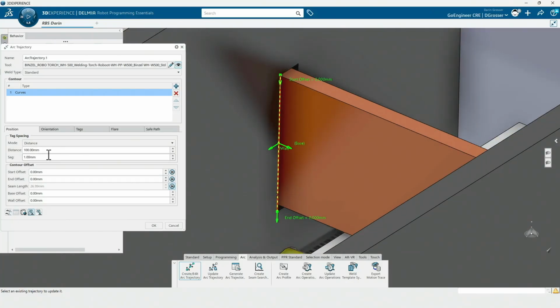From there, we've got our start points and our end points. And when we're defining things, if you're comfortable over here, you can define the start offset, the end offset, and the overall length. One of those three always has to be driven, though. So you have to choose whether you want to have offsets drive the length or one length and one offset drive the other offset. But there are on-screen handles, and if you're just a little bit explorative, you can see that there are arrows out there. That should be enough to drive you to start clicking on things as well.